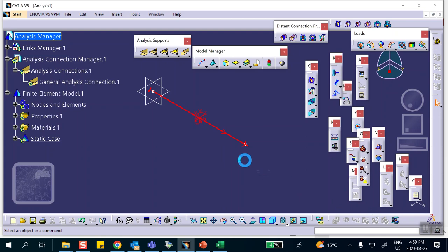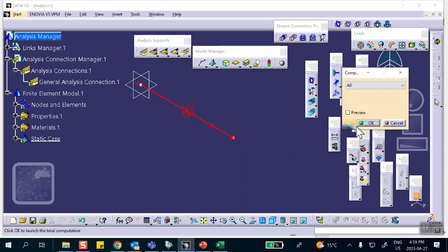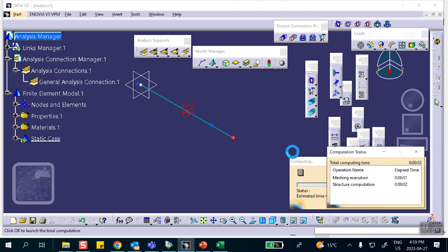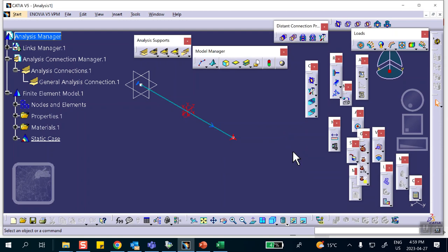So obviously, if the stiffness is 4 and you pull this thing by 1 Newton, this is going to deflect by 0.25 meters. Okay, so let's go ahead and run it. Nothing exotic is going to happen. Good, and if you look at the displacement, all you see is 0.25 meter.